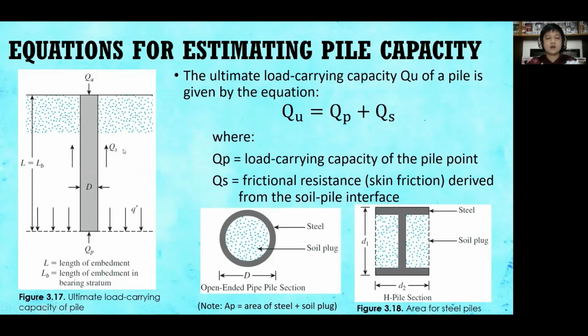So for our pile case, Q is equal to gamma prime multiplied with Z, that is L. This is related to our discussion of shallow foundation, where Q is equal to gamma times dF, the depth of footing. For this case, our depth of footing is the length of the pile.